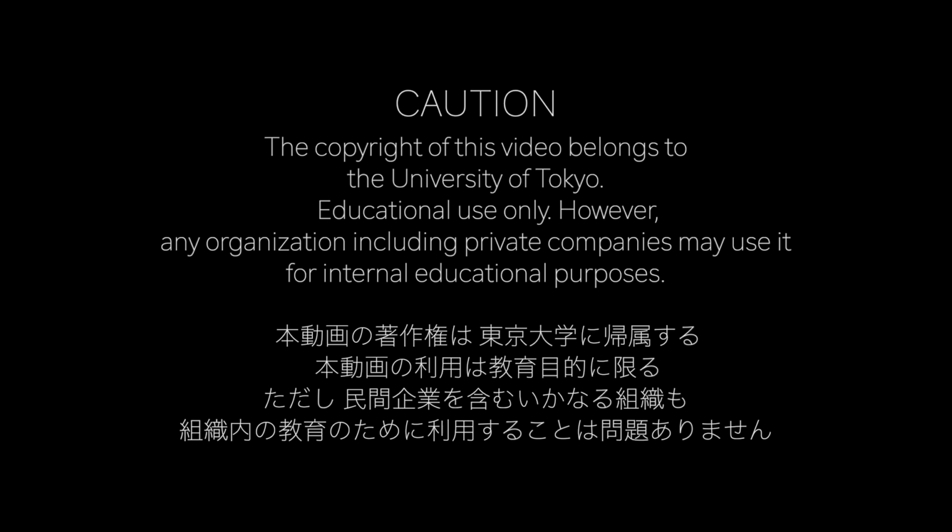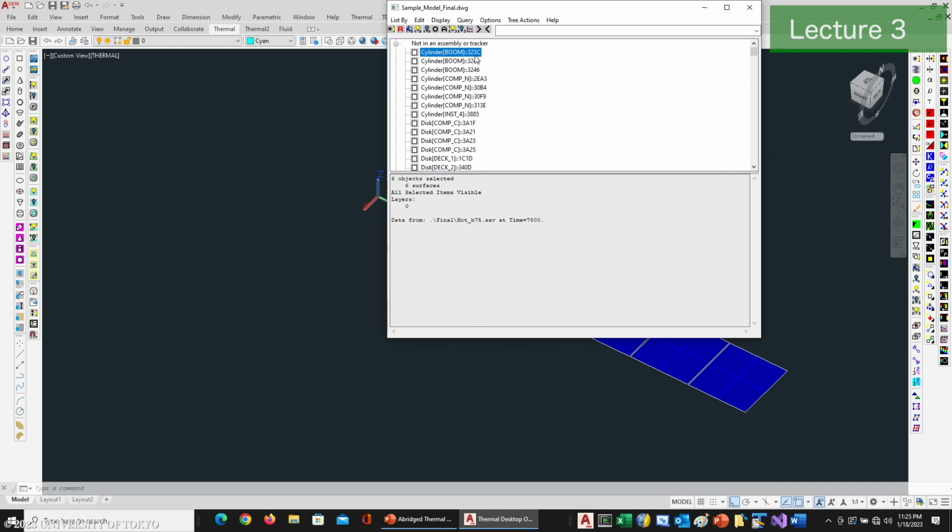There's also an option in Thermal Desktop called Fast Spin. So if you have a rotating reflector or something like that, or a dish that's moving quickly, many revolutions per orbital position, you can set it up such that you have that assembly, it's tied to a symbol, and then you can set the fast spin option in Thermal Desktop to say, I want you to change this symbol, go through 12 different positions and fire 5,000 rays at each position.